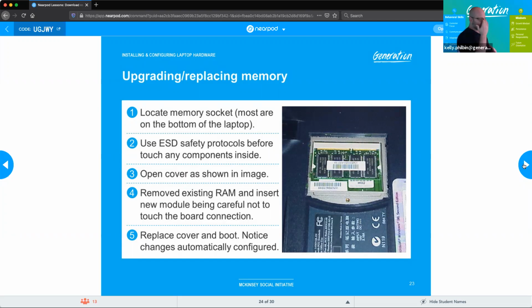And the way the laptop memory sits in, it's kind of weird. If you remember on a desktop, they just laid in vertically and just docked in, and it stayed that way, just perpendicular to the physical motherboard. In a laptop, it doesn't operate that way because they don't have that kind of space to maneuver in. So the actual port for the memory in the laptop is on a hinge. So you will actually lift them up and you'll pull them out, and then you'll set a new memory slot in, and then you'll lay them back down. So they almost lay down like dominoes on top of each other when sitting inside the computer.